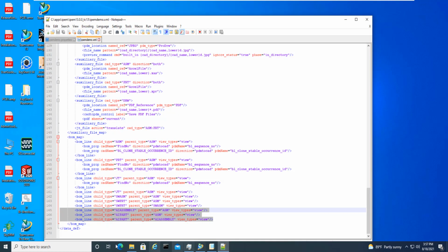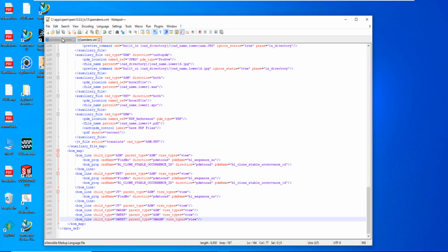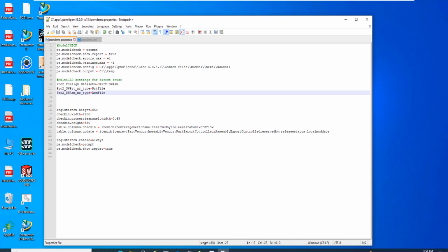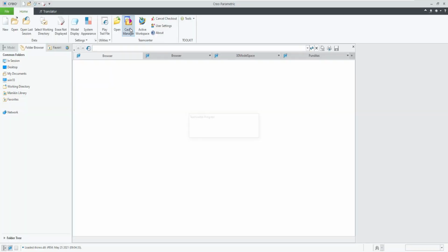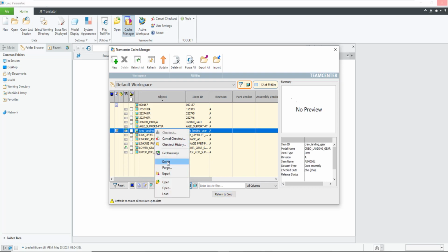What can be done? I still want to reuse the Inventor design in my Creo assembly. We can revert to indirect JT-based reuse simply by removing all references to Inventor datasets from the IPEM.properties and IPEM.xml files. Configuring Inventor for hybrid reuse is not an option, because Creo will not even open the Inventor part files via the API.